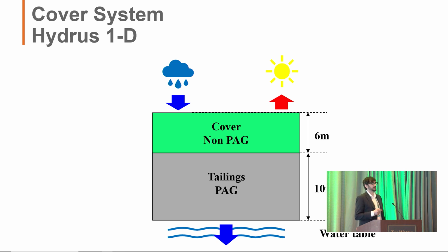So it is important to say that in this exercise, we are considering slurry tailings. That means that at the beginning of our simulation, we will have a fully saturated profile, which means the degree of saturation is 100%.